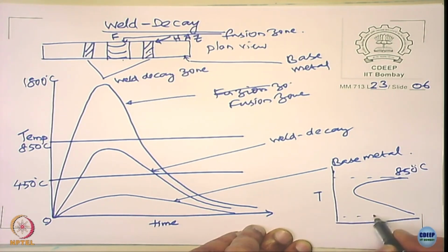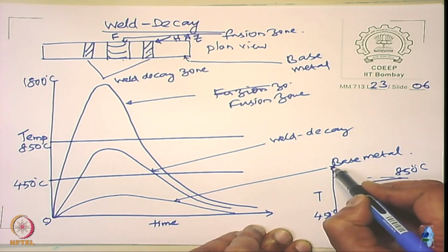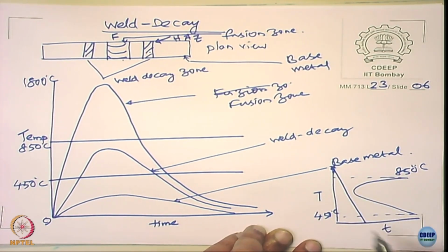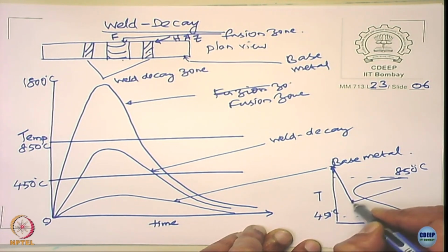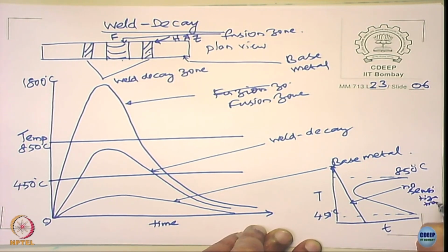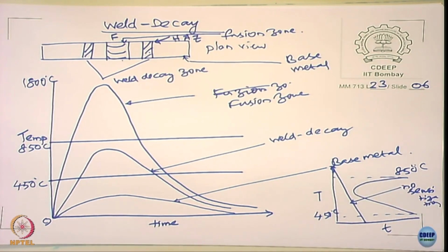What is this temperature? 450 degrees Celsius. If I take it to this temperature and quench it very fast, no sensitization, right. Or I put it the other way around, if I can draw a nice thing.